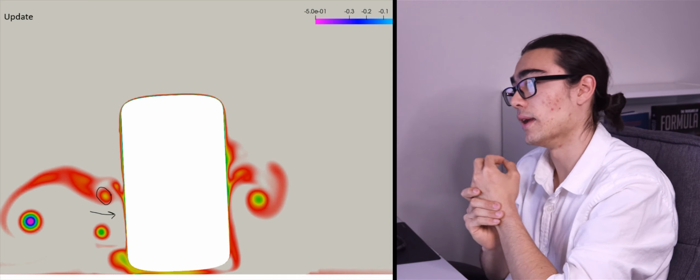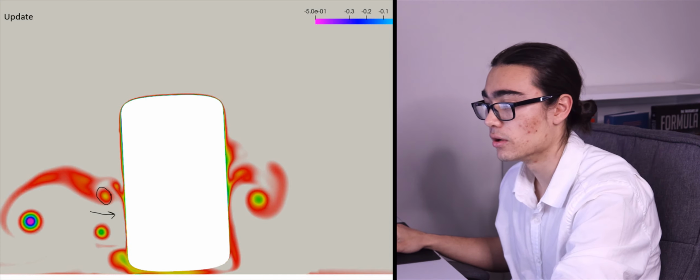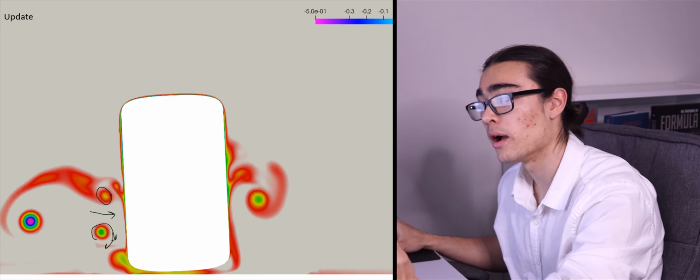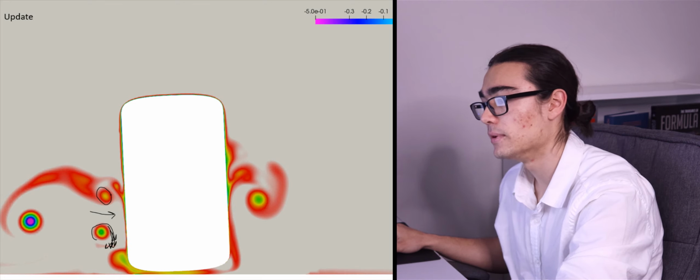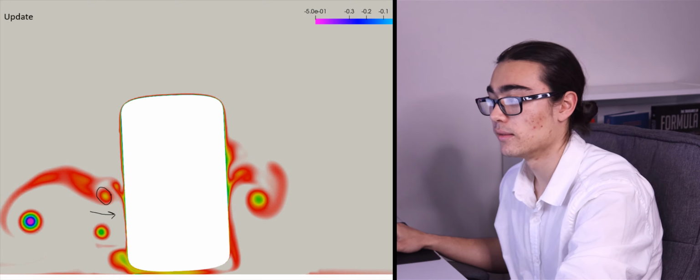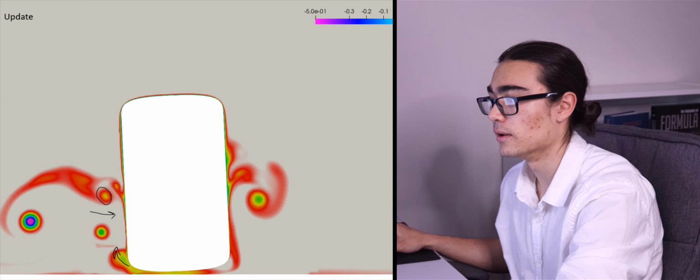The lower vortex is in much more of a position to begin working with the squirt here. Hopefully not drawing it in too much because it is quite high off the ground, but actually adding some momentum this way and potentially dealing with this squirt coming up and outboard.